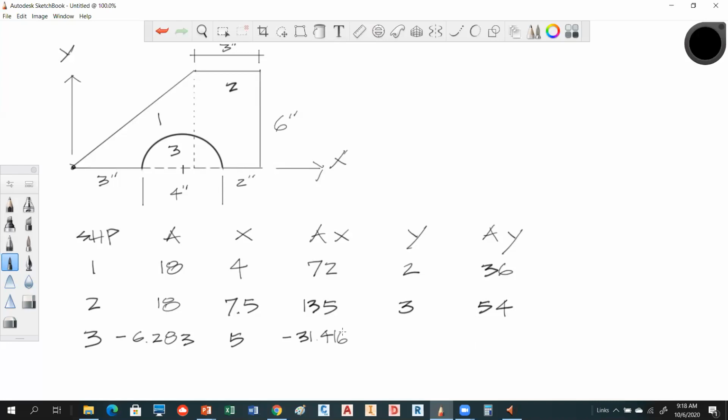And then we have the y value. Now the y value is going to be that distance above, which it shows you on the chart. That's going to be 0.4244 of r. So 0.4244 times 2 gives me 0.849. Does that sound right? We good?